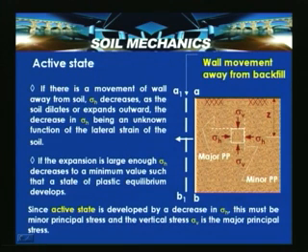And here again the element considered is sigma v and sigma h at a depth z. Now, if there is a movement of the wall away from the soil, then sigma h decreases. Please note down, the horizontal stress decreases as the soil dilates or expands outward, the decrease in sigma h being an unknown function of the lateral strain of the soil. So, as the wall moves away from the backfill, the soil dilates or expands outward.